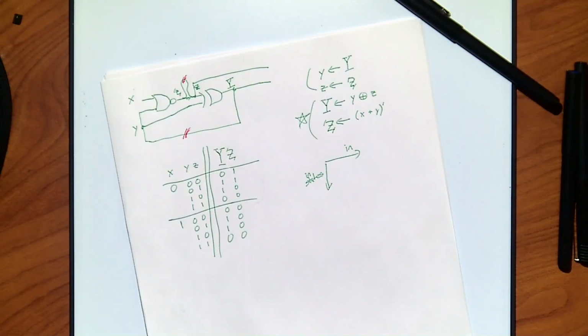These are my states. This is actually what we want, right? With asynchronous things, we want these states to be very, very fast. The only reason you would ever go to asynchronous is you need stupidly fast states, right? Regular states just aren't quick enough for you, and for whatever reason, you need them ridiculously fast. So this meets some type of requirement. So we know these, by putting the labels on the rows, I put all the fast ones there. How about the inputs? How fast are the inputs?